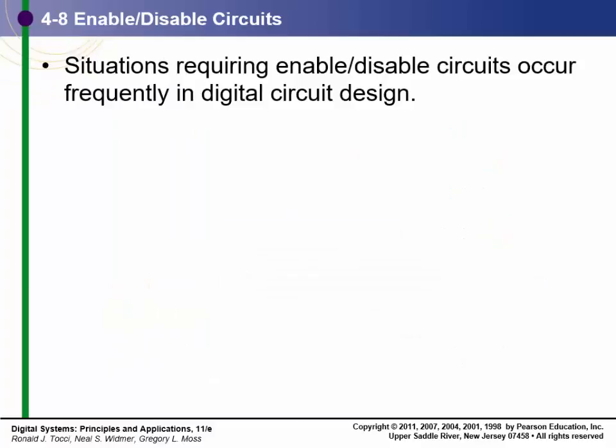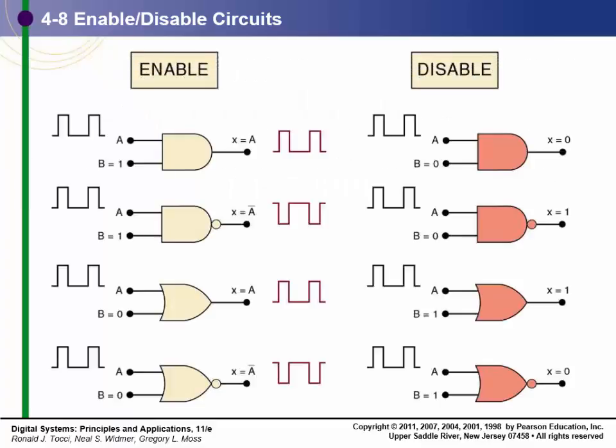So we haven't talked much about this particular subject. I want to just kind of go through it. We will see certain circuits that will have enable or chip inputs. This is showing here, for example, that I'm using B as an enable in order for this to go through. If B is equal to 0, this signal does not pass. That is all this is saying. We use an AND gate there as an enable pin.